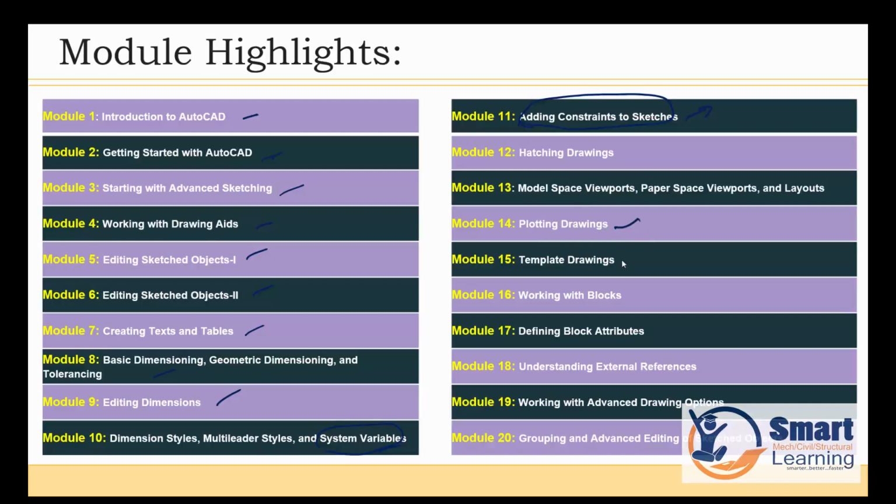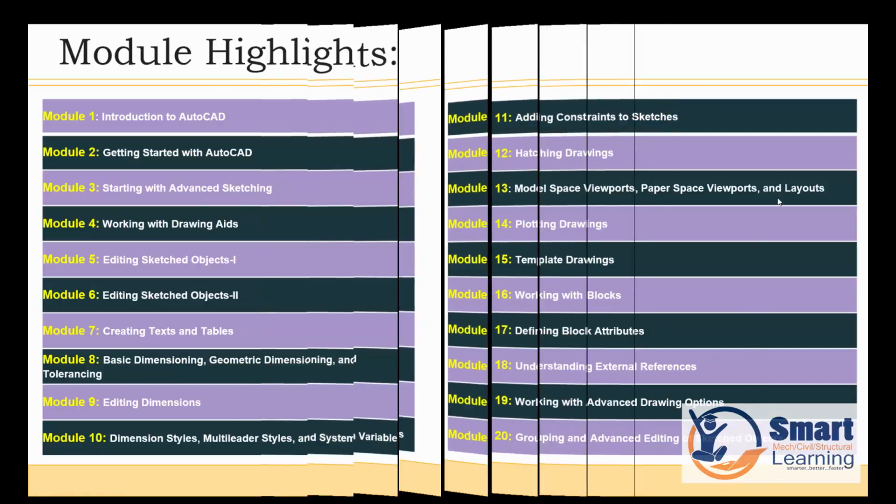Hatching drawings, model space viewport, paper space configuration and layout, plotting the drawings, and template creation for your companies and for different purposes. Working with blocks, and how you can increase productivity by reusing objects. Defining attributes and the block, a very advanced concept. Understanding external reference, also a very advanced concept that we'll be dealing with. Working with advanced drawing options, and finally we'll look into grouping and advanced editing sketch options.